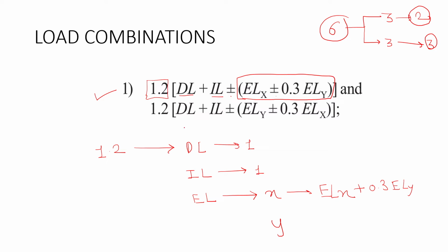Similarly 1.2 full dead load, full imposed load. Now here y direction is dominant, hence earthquake load in y direction is full and 0.3 earthquake in x direction.